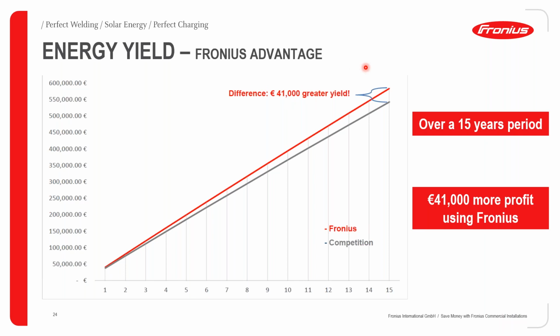So when you do your system simulation using professional tools such as PVSYST, you can see clearly which inverter choice you should go with. Therefore, we always recommend that you use an actively cooled inverter, because even the derating behavior when the ambient conditions are above certain thresholds is very different on a passively cooled inverter, which derates earlier, compared to an actively cooled inverter. In our case, the inverters can start derating at ambient temperatures of up to 50 degrees Celsius.